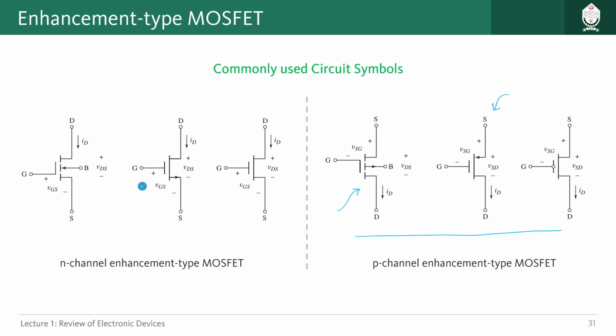But one thing you have to understand, the difference between P channel and N channel is generally that for N channel you give positive VGS and current flows from drain to source as you give positive VDS. Here, as you can see, source is at a higher potential compared to drain. So we have given what? VSD as voltage, and also the gate voltage we will apply will be negative.